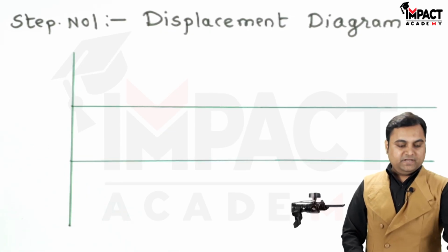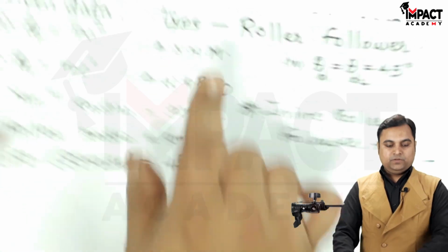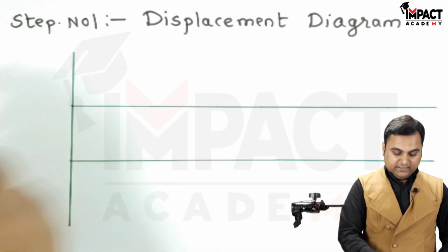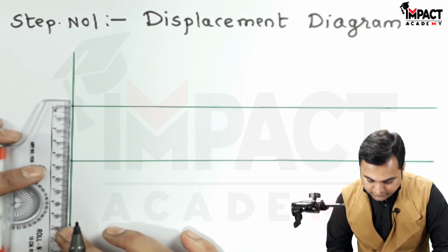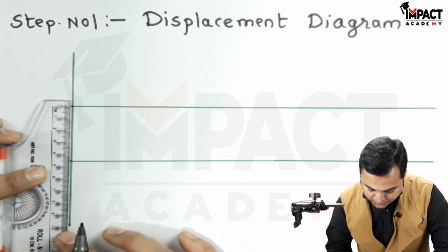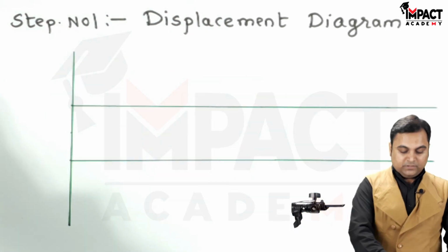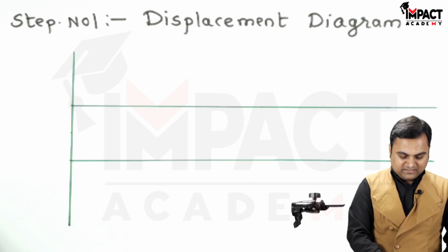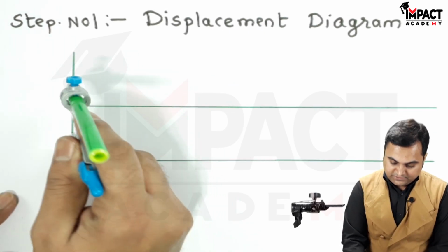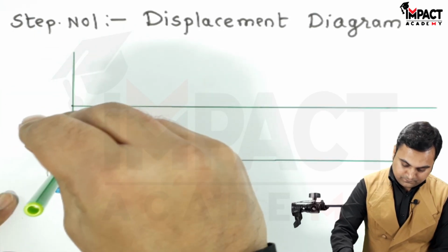It is mentioned that the outstroke is with S.H.M. For that, take half of this lift or height. It is 45, so that is 22.5, and mark the center. Then from this center, draw a light semicircle, keeping this center and a radius equal to half of the lift.